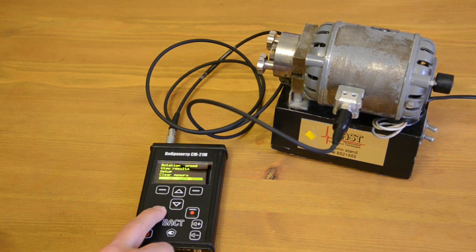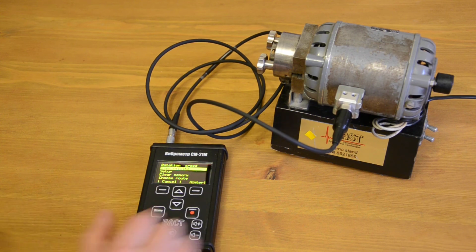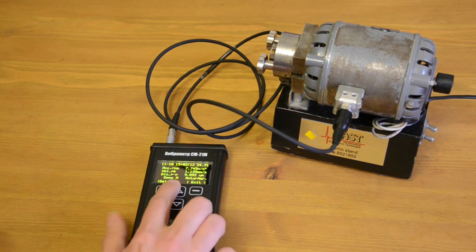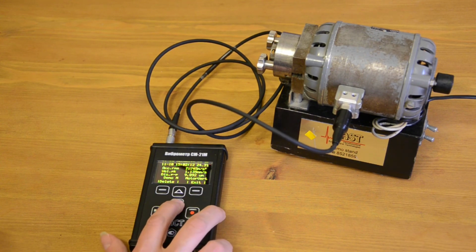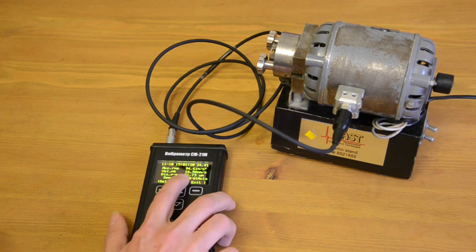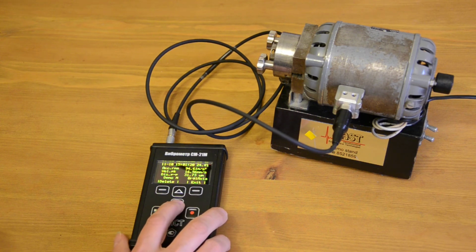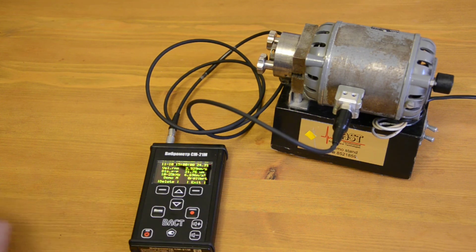We can go back to the menu and, for example, review the results. Here is a command, view results. We can enter it, and we see that we have demo motor, motor horizontal. This is the numbers for vibration. This is the motor vertical. This is bearing 1 axial, and you see that in velocity we have quite a big velocity, 16 millimeters per second, and we have 2 millimeters per second in horizontal, and we have velocity 2 millimeters in vertical. So this is the measurements that we can do according to the route.